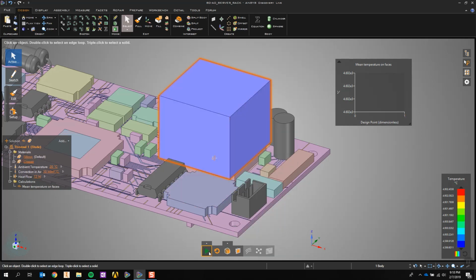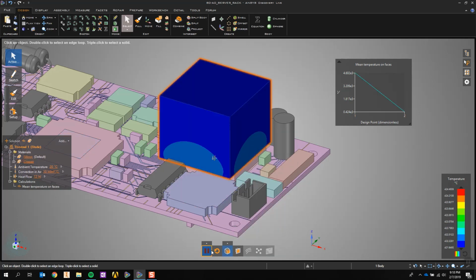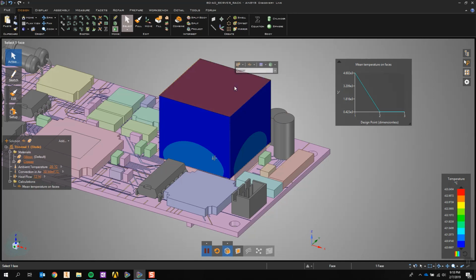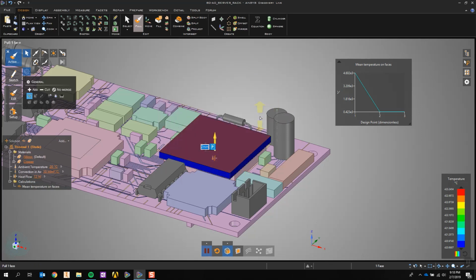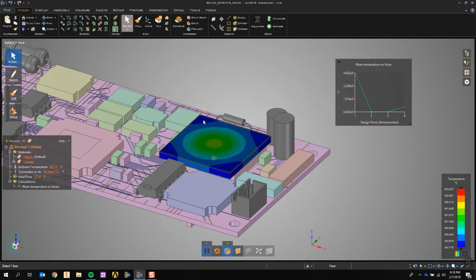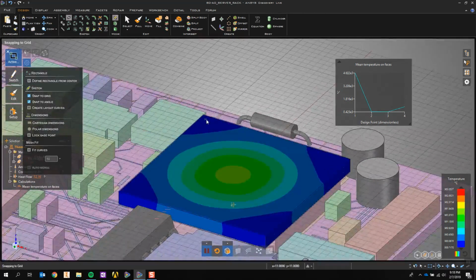Discovery Live allows us to select specific parts in our assembly to be in the simulation. For this instance, we have selected the silicon chip and heatsink. Therefore, the simulation results and design changes will only be captured for these 2 parts. You can see that even adding a block of copper lowered our temperatures significantly. We will further optimize our design by adding pins to a thin base plate. This will give our heatsink more surface area to convect the heat.